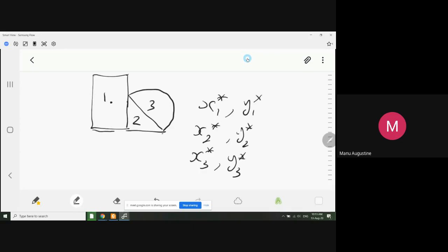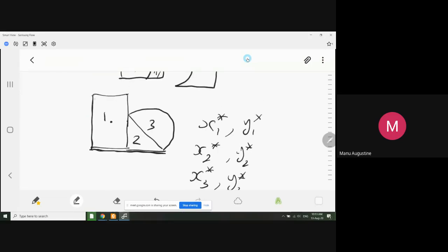So the most popular method of selecting the origin, if it is not given in the problem, is to select the bottommost leftmost corner of any given figure. So it is convenient in this present scenario to put the y-axis here and the x-axis here. Since it was not given in the problem, I am selecting it on my own. And how do you do that? In the question paper or in the answer paper, while you answer, you draw this figure, you draw the coordinate axis and put a capital X and capital Y here and put an O mark here to show that this is the origin.